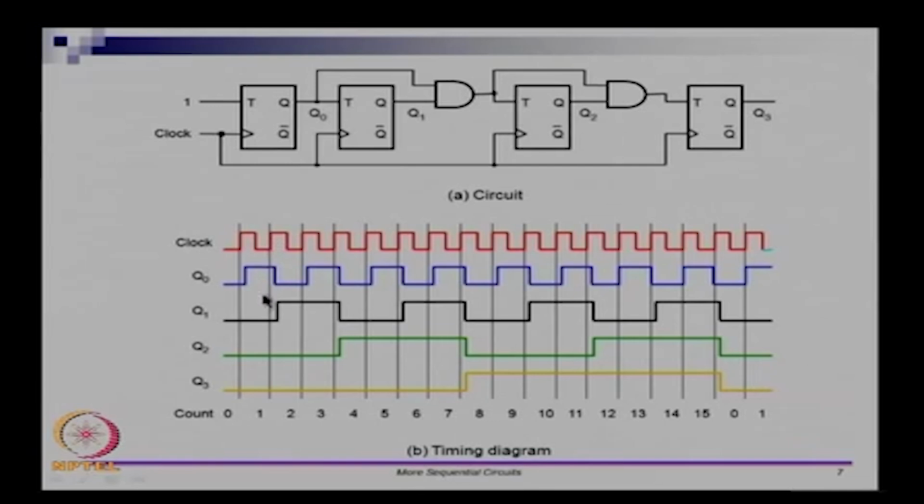So, with respect to this clock, you look at its input, the input is Q0, right. Has it settled down? Yes, it has settled down, which means Q1 can flip a clock to Q delay away from this clock, not from Q0, right. So, Q0 is data to Q1 and clock is the input clock signal itself.